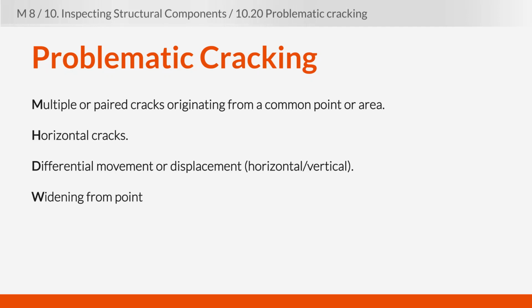Anytime the crack gets wider from the point of origin, that's not a good sign. And vertical cracks. I did say earlier a lot of times vertical cracks were typical, but when they're exceptionally large, they're no longer typical.